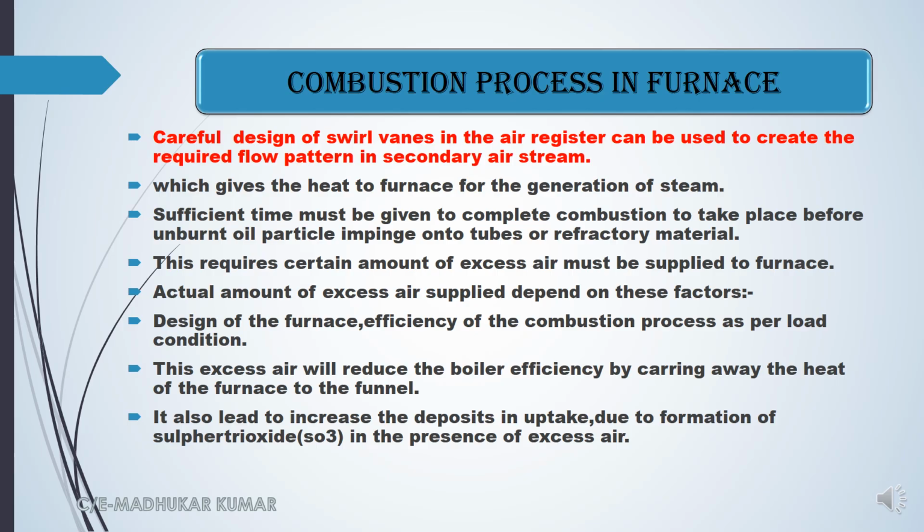Sufficient time must be given for complete combustion to take place before unburned oil particles impinge on the tubes or refractory material. Basically, if the suspended flame length is more, then along with the secondary air, the droplets will impinge on the other side, on the refractory material opposite the burner front, and this creates deposits. So a certain amount of excess air must be supplied. For that, we have to make sure a little bit more air is supplied so that proper combustion takes place. So this is also kept in mind.